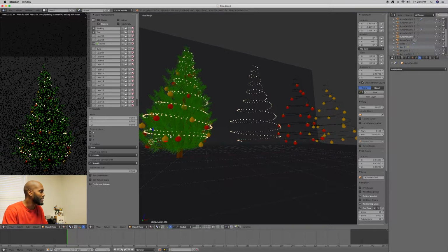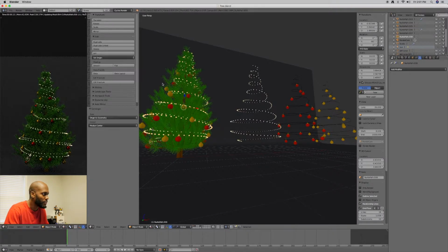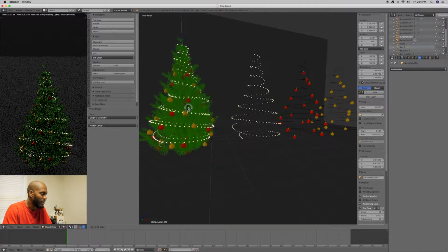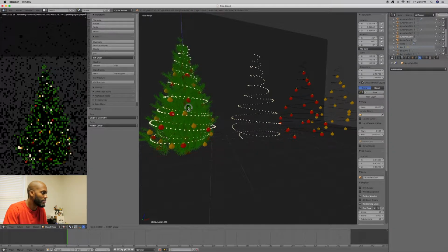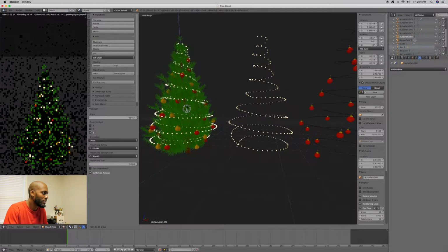And we're going to actually do a tools, do the center to geometry or origin, what they call it in Blender. And we're going to rotate it 90 degrees or 45 degrees or something where it doesn't match. So we want kind of like a double row.